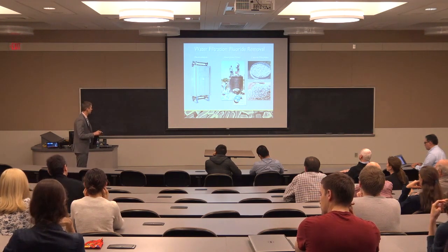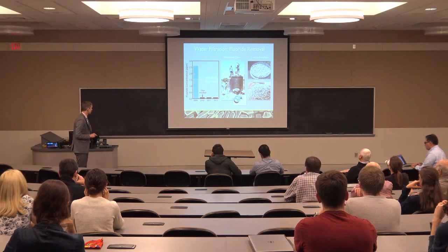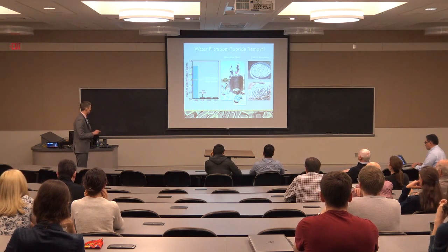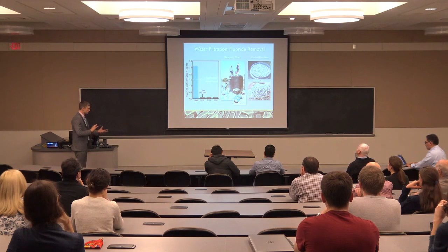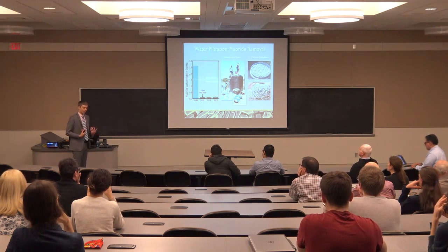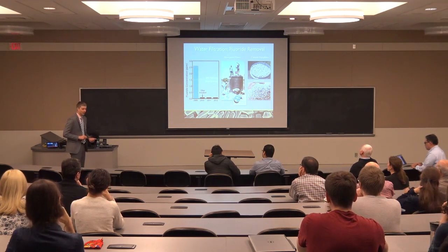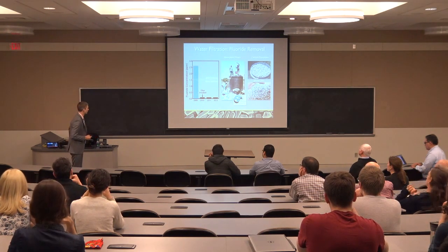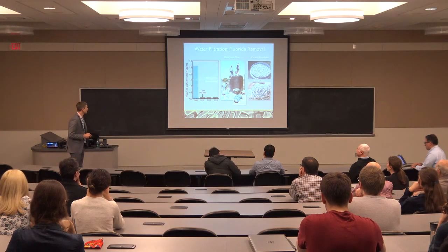And so we worked with this community to implement some of these filters, and it works. So this is the fluoride level when we started out. This is the drinking water standard from the World Health Organization, and after we installed the filter, the fluoride levels dropped quite a bit. So this is sort of an example of, we wanted to prevent the absorption in the body, and so we used the apatite structure that's present in this bone char material to absorb the fluoride beforehand, so we don't end up consuming it.